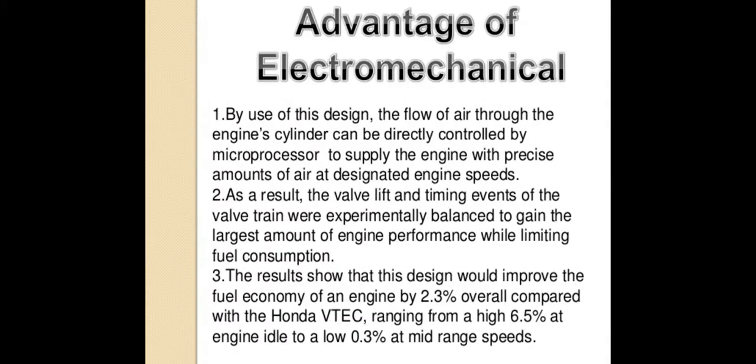Advantages of electromechanical. By use of this design, the flow of air through the engine cylinder can be directly controlled by a microprocessor to supply the engine with a precise amount of air at designated engine speed. As a result, the valve lift and timing events of the valve train are experimentally balanced to gain the largest amount of engine performance while limiting fuel consumption.